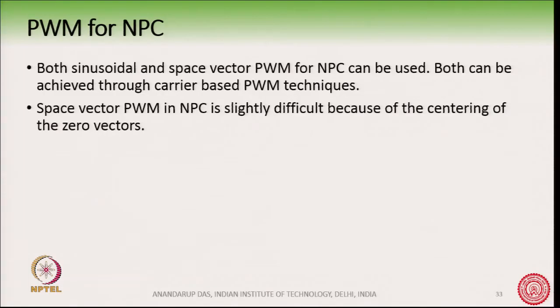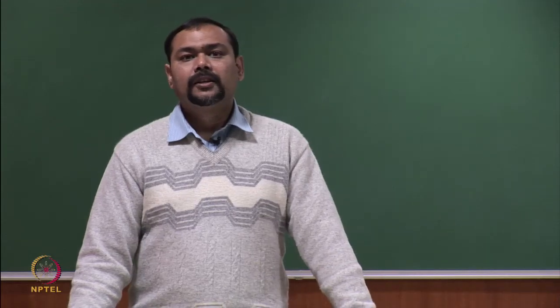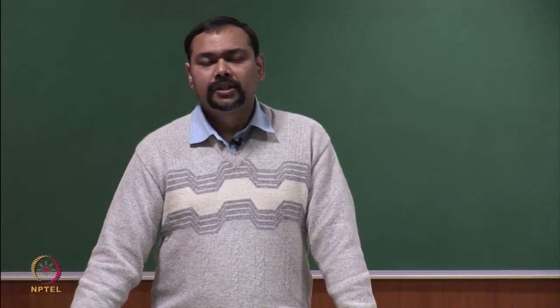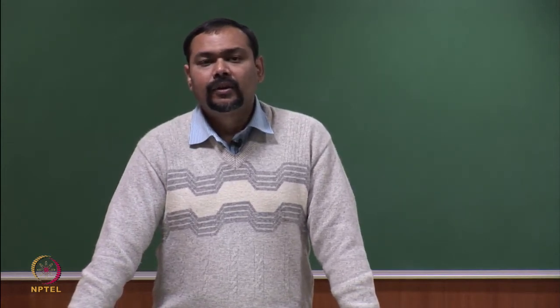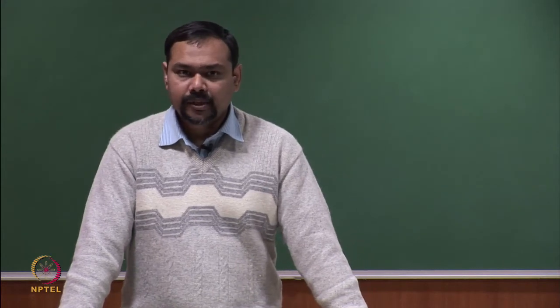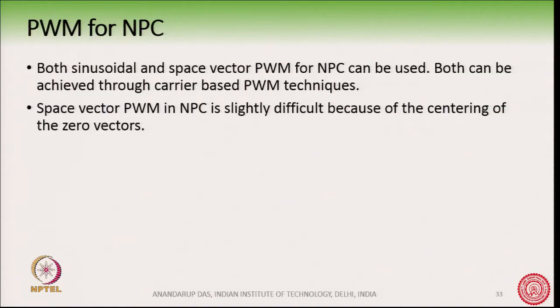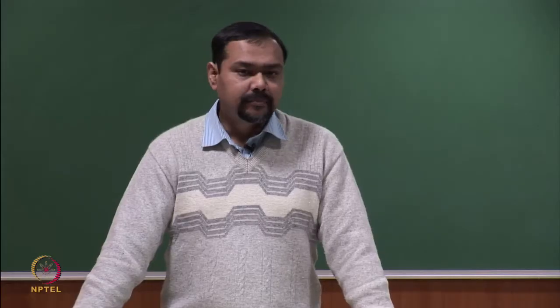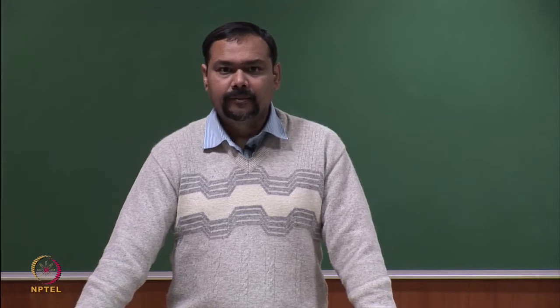Okay. So, we now look into the PWM or pulse width modulation strategies for the neutral point clamp converter, specifically the 3 level NPC. For switching NPC, we can use both sinusoidal as well as space vector PWM, and both of them can be achieved through carrier based PWM techniques.